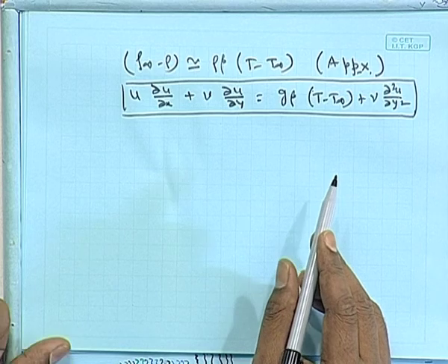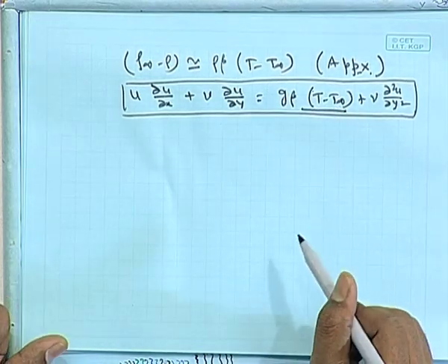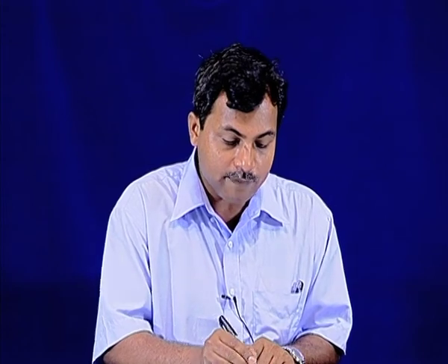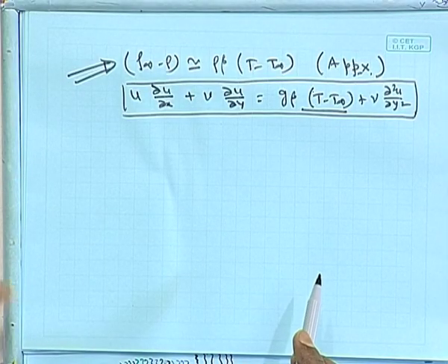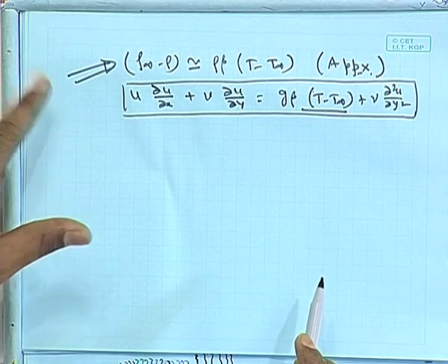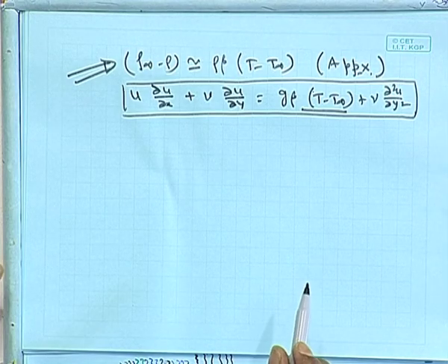Now see, in case of natural convection, you will be having an extra term, which is basically the buoyant force term, which will be a function of density, which is in turn a function of temperature. By using this approximation, you can express that function of temperature as a linear function, as an explicit function of temperature. The variation of density difference can be related explicitly with temperature.